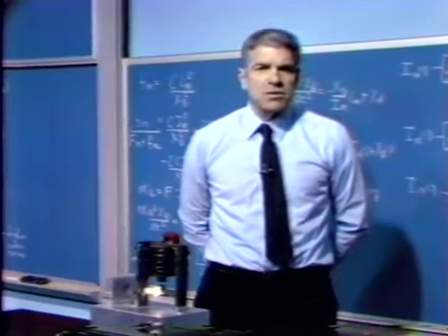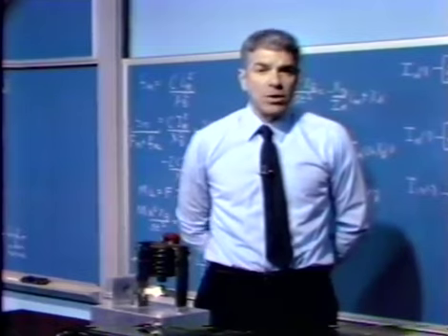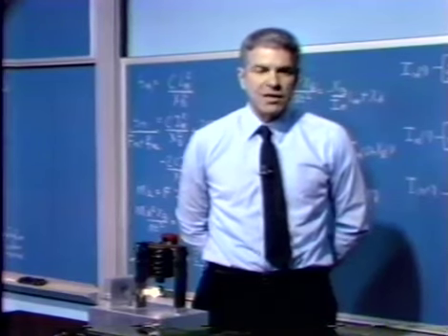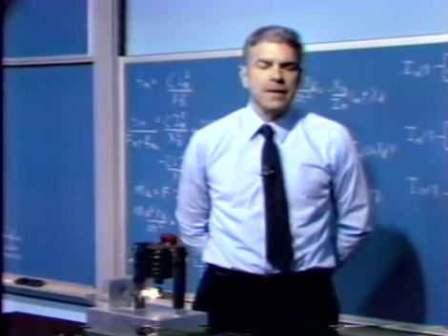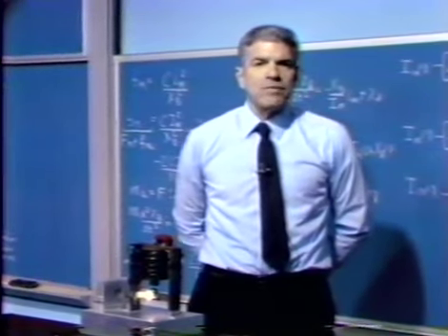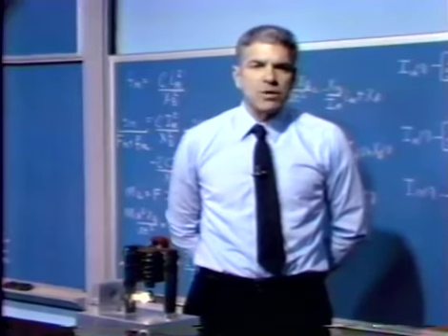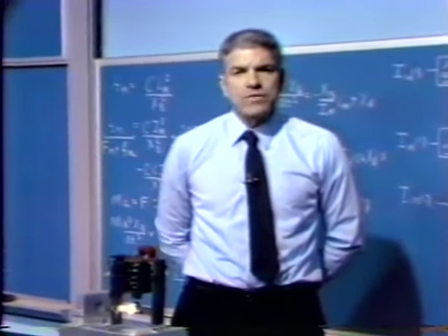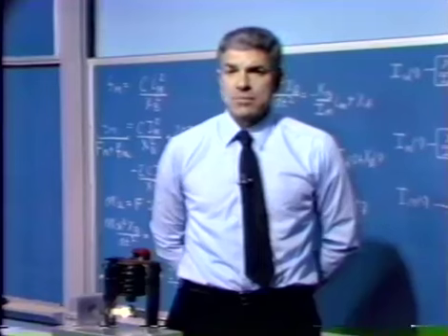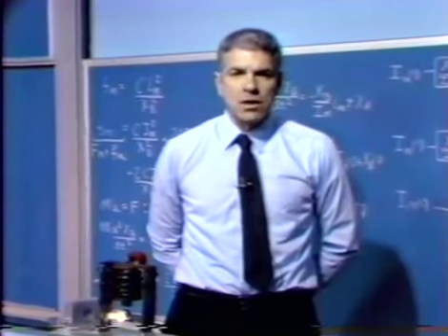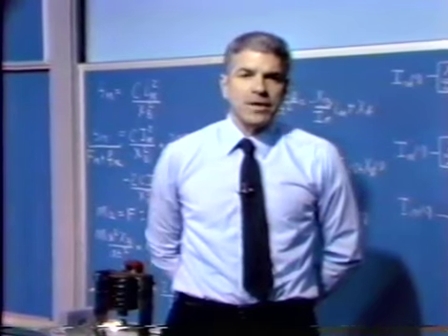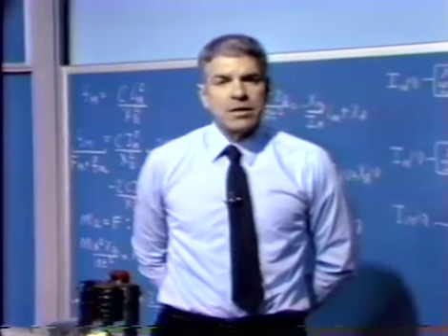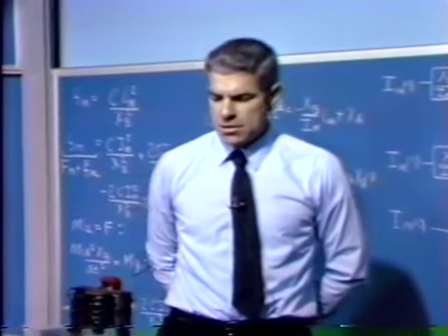The dynamics associated with the ball and the magnet have a pole in the right half plane, and we certainly anticipate then unstable behavior unless we do something to counter that right half plane pole. So we've seen that behavior. We've then used our root locus approach to give us a quick look at what we might do to improve the situation, and we've decided on a compensation strategy based on that. In particular, what we'd like to do is add a zero to the loop transmission, and hopefully then by combining the zero with an appropriate amount of A naught, we're able to stabilize the system.